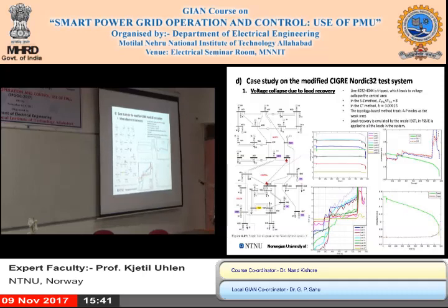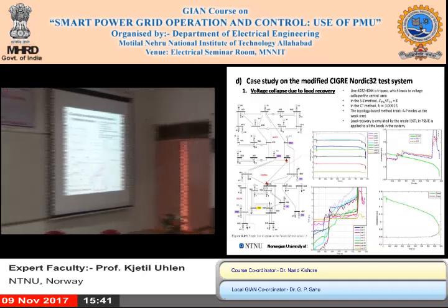Here, they would have seen that the system is in trouble. It has already reached the maximum loadability, but they kept on running the system until it collapsed over here. So this is to indicate that this indicator is useful, because it could have given them time to shed load to avoid the collapse if they had that information at that point. So that's the main message on this one.